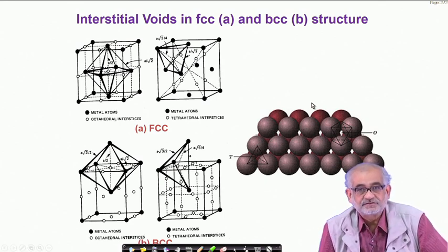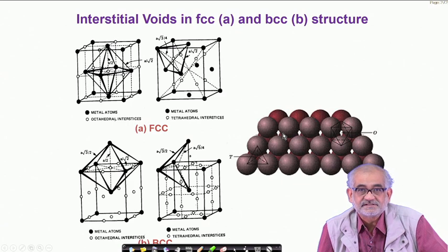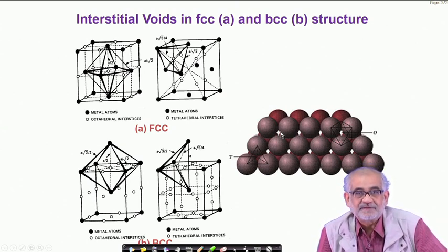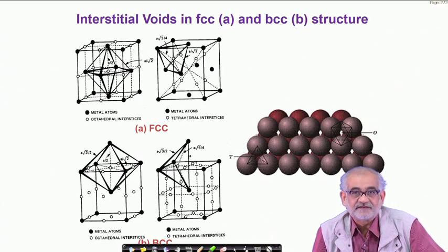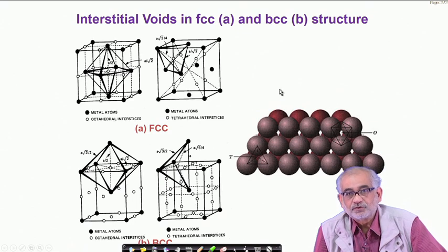The packing density can have very specific values depending on the structural motif that we have. What is important is to realize that the open spaces will also have a very specific geometry, simply because the hard spheres have their own sizes. If the spheres are of the same size, then the packing density can take very unique values. For example, the maximum could be 74%, or else it could be 68% if it is BCC, and so on and so forth. But what about the open spaces?